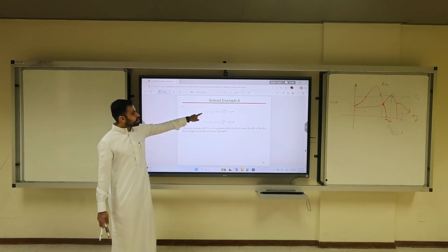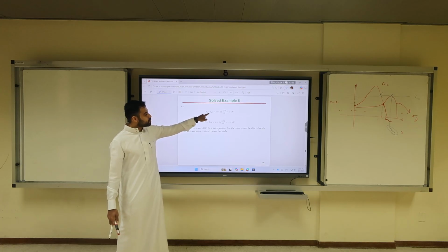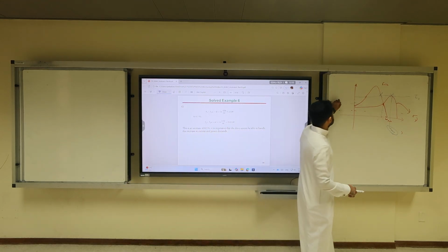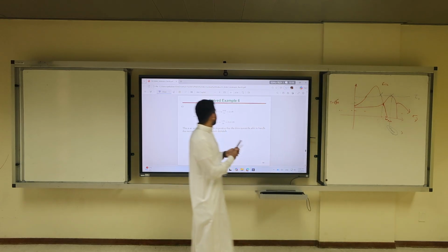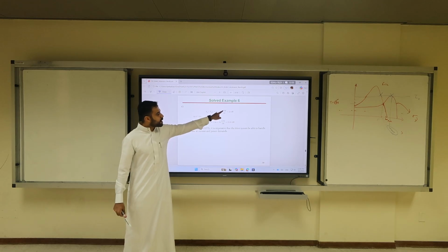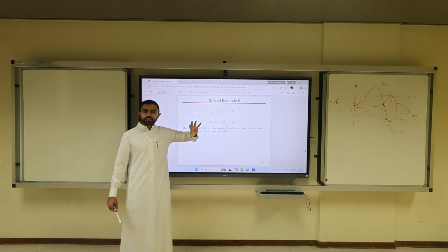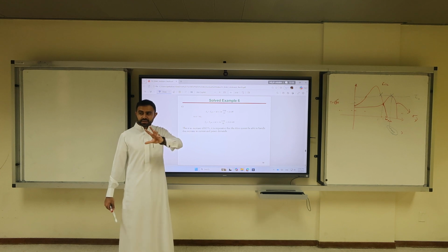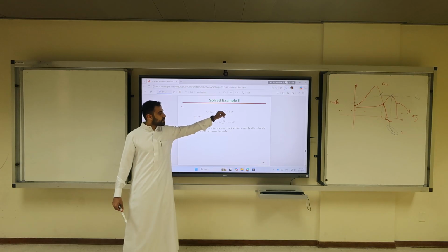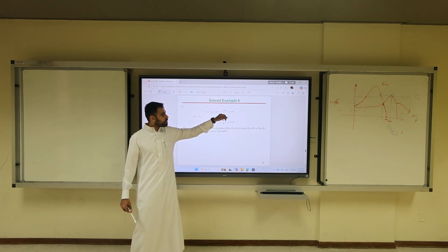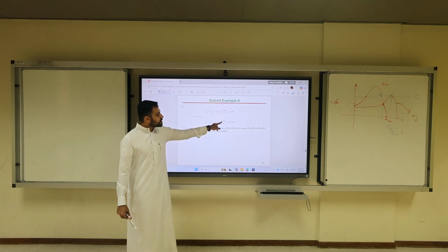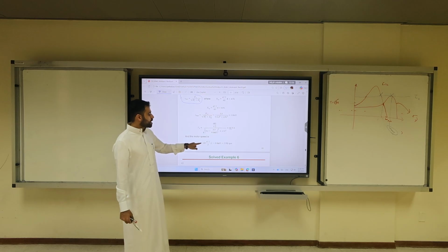Developed power is developed torque times omega. Sorry, this is not 180, this is 60. Developed power is 60 times omega, which is 2 pi times rated speed. This is developed torque, not air gap, not magnetic torque. So omega rated is 3500 times 2 pi over 60, times 60, this is 22 kilowatts. At 67 hertz, the speed is 3792. That's the speed.